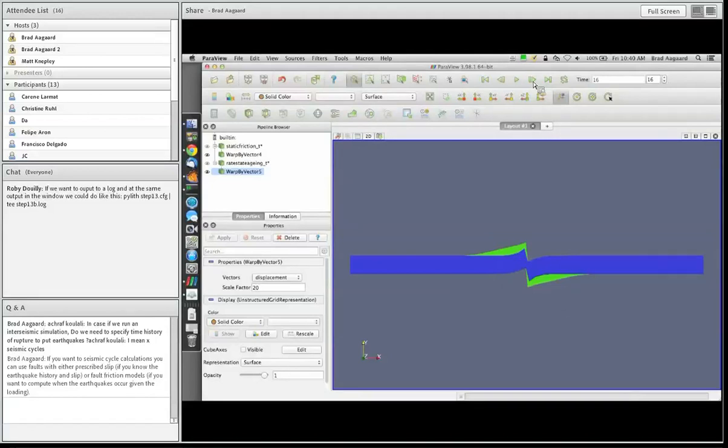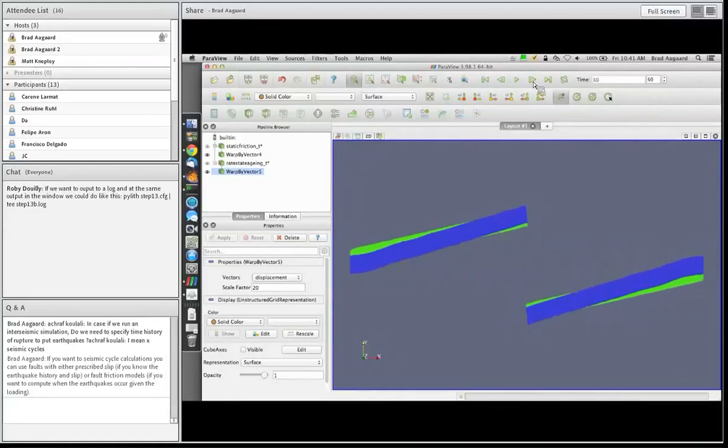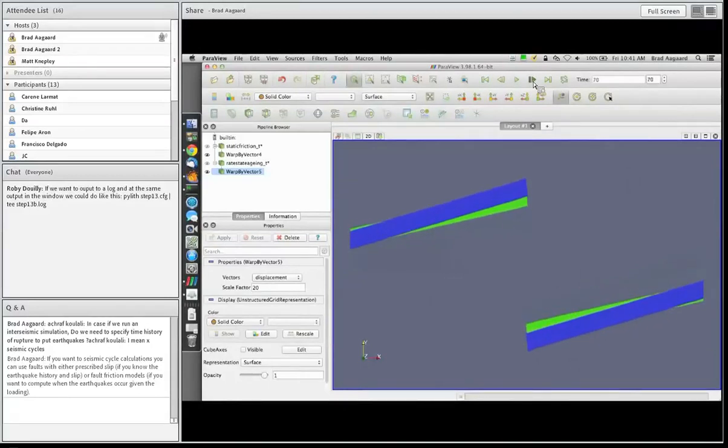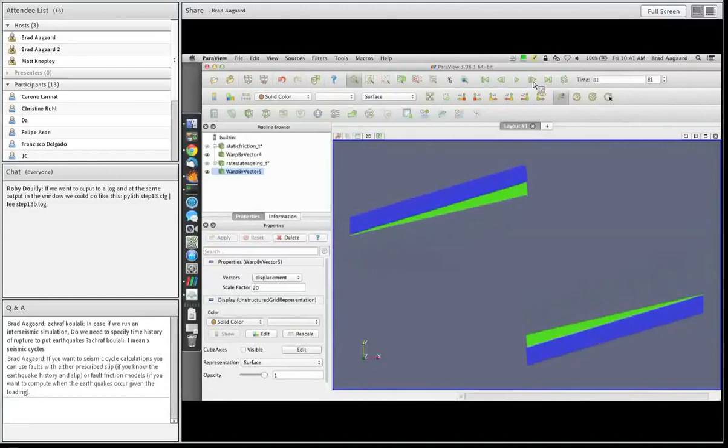And so initially we start slower than using a static coefficient of friction of 0.6 because of the direct effect. As we weaken, you'll see here we're going to actually catch up to the static case, and then we'll exceed it because we have a larger velocity due to the fact that the fault weakens, and so our coefficient of friction is below 0.6. And in both cases, we're going to get steady state behavior, and so with the faster velocity, greater weakening, I end up with more strain in my bar because I need to still exactly counterbalance my prescribed tractions. So there's the rate state case in blue and the static friction case in green.